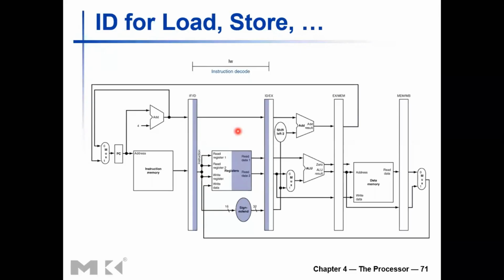And as you have asked earlier, the control signals that you generate in this stage must be preserved because they will be used by later stages, right? So those control signals or control bits need to be stored in the next pipeline register, the IDEX pipeline register, and used in the EX stage or the MEM stage or whatever comes afterwards. So you need to preserve those control signals.